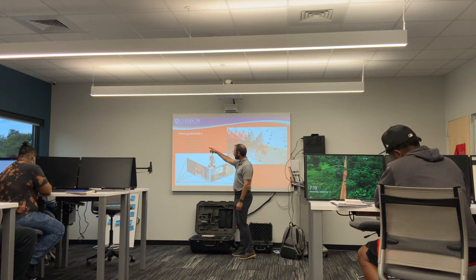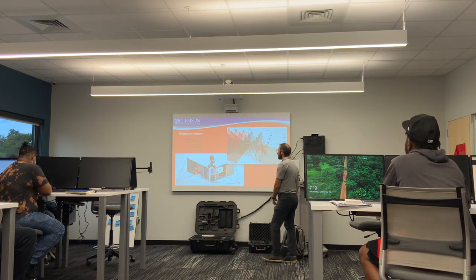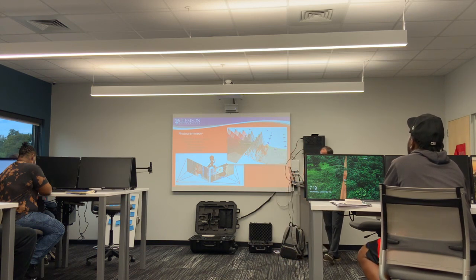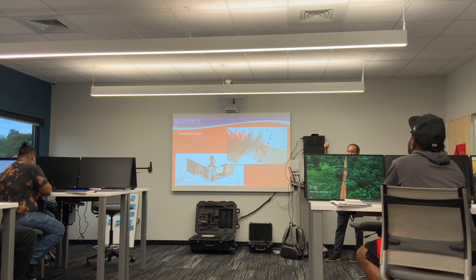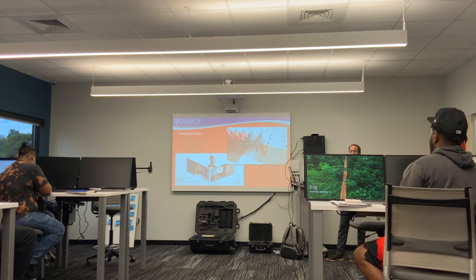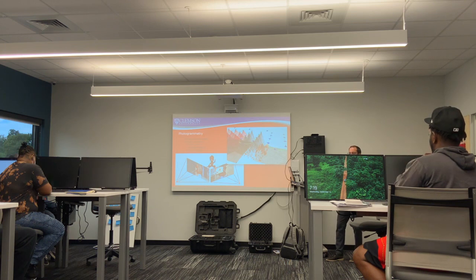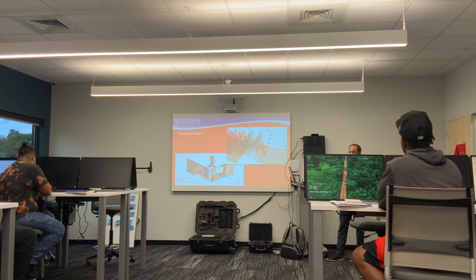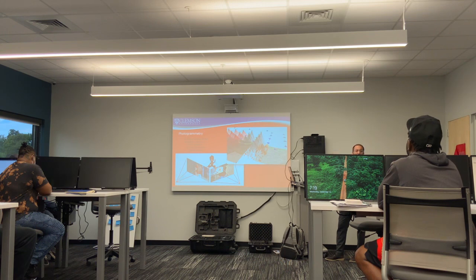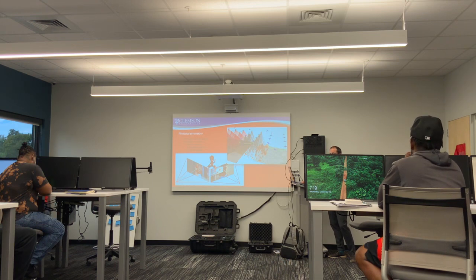So like we said, the metadata in the photos includes the GPS location, the compass heading, the camera angle. All the images that we did on this one were nadir, straight down. So when we pull up the photogrammetric mesh of what we did, the building won't be very sharp, because we didn't get any oblique images. So you'll see the impact of that. You can go ahead and do oblique images. There's a mission type to include obliques. It just takes a little bit longer, more photos, more time, things like that.